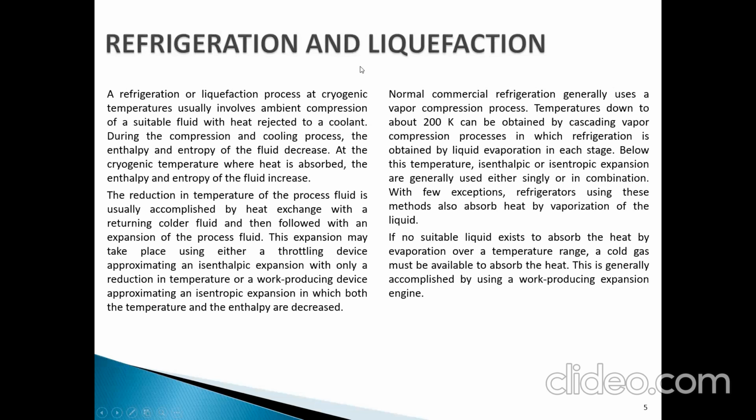Refrigeration and liquefaction. A refrigeration or liquefaction process at cryogenic temperature usually involves ambient compression of a suitable fluid with heat rejected to a coolant. During the compression and cooling process, the enthalpy and entropy of the fluid decrease. At the cryogenic temperature, where heat is absorbed, the enthalpy and entropy of the fluid increase. The reduction in temperature of the process fluid is usually accomplished by a heat exchange with a returning colder fluid and then followed with an expansion of the process fluid.